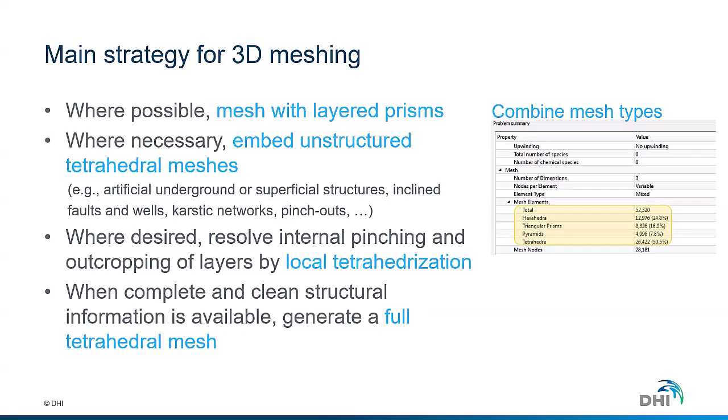So what we recommend in general, if you have simple geometries or simple geologies, is to just work with layer meshes, because this is something which FEFLOW has been doing since the 70s, and we have a very robust workflow.